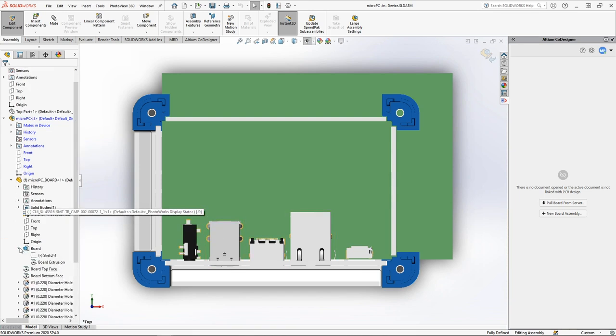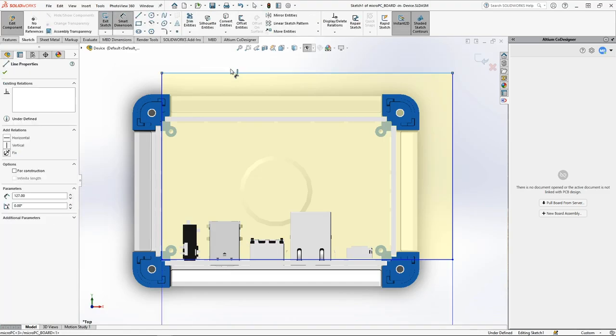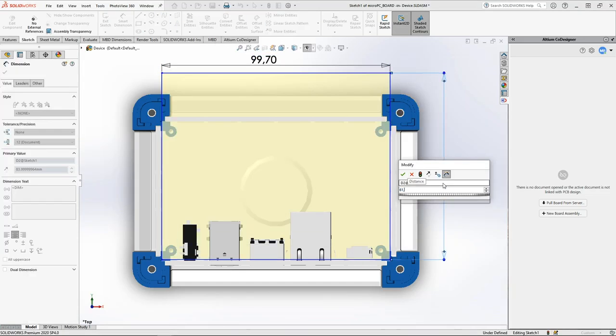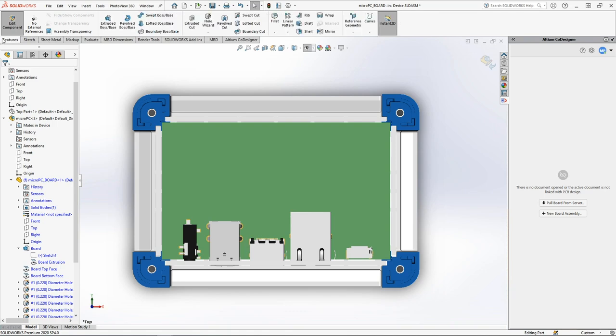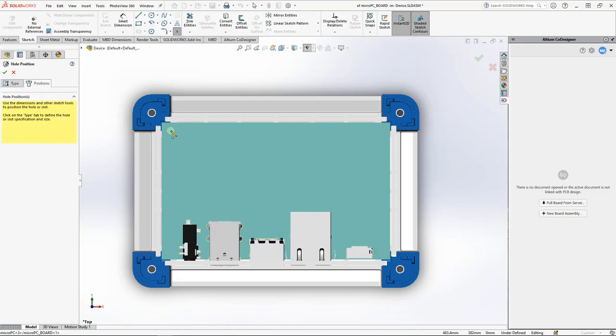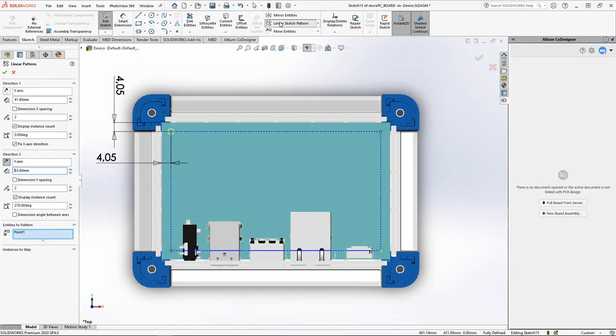The shape of the PCB can be easily changed by editing the sketch inside its component. You can create board outlines of any complexity using the tools in your MCAD. You can also place holes of any desired standard and size, using convenient and familiar tools from the mechanical engineer. In the context of device assembly, you will immediately see the result of their placement.